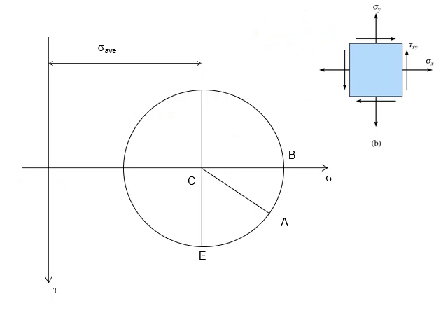Okay. So in other words, this is what you do. When we look at this stress element here, sigma x is positive, sigma y is positive, and tau xy is a certain value, right? Now, if we try to determine from this, we will say that most probably the circle is going to be on the right of the vertical axis or shear stress axis. It's going to be on the right. How far right depends on sigma x, sigma y, and tau xy.